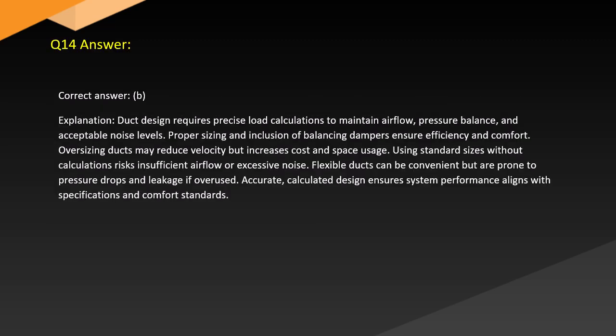Answer. Correct answer: B. Explanation. Duct design requires precise load calculations to maintain airflow, pressure balance, and acceptable noise levels. Proper sizing and inclusion of balancing dampers ensure efficiency and comfort. Oversizing ducts may reduce velocity but increases cost and space usage. Using standard sizes without calculations risks insufficient airflow or excessive noise. Flexible ducts can be convenient but are prone to pressure drops and leakage if overused. Accurate, calculated design ensures system performance aligns with specifications and comfort standards.